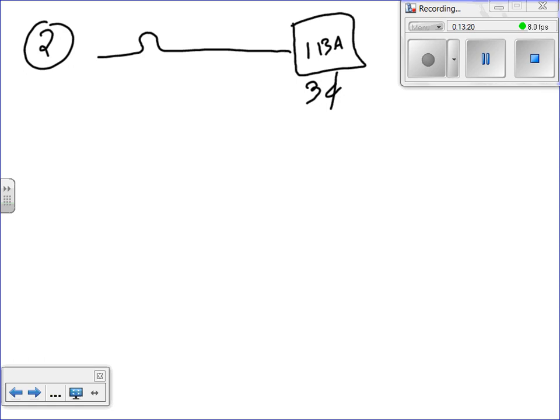By the way, did I say anything about voltage in the first example? For all practical reasons, your voltage in that example could be 240, could be 120, could be 480, could be any voltage as long as it's 600 volts or less, because almost all the conductors are listed for 600 volts or less. If you look at any of these conductors in front of me here, they're all rated for 600 volts. What does that mean? The same calculation I can do for any voltage up to 600 volts. That's why I didn't put any voltage for these.